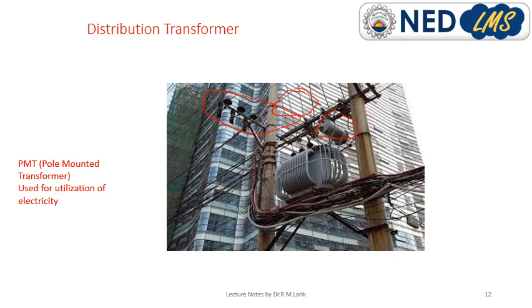Three wires are three phases, red, yellow, blue, and the fourth wire is neutral, and the fifth one is for the earth, for protection. Neutral is needed on the secondary side to feed the consumers: a single phase consumer is fed by phase and neutral, and a three phase consumer is fed directly by three phases.